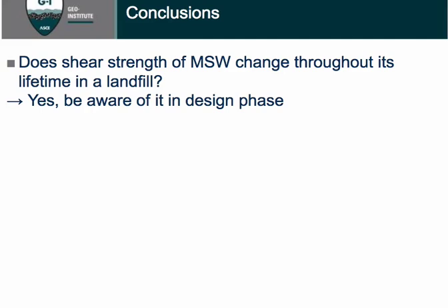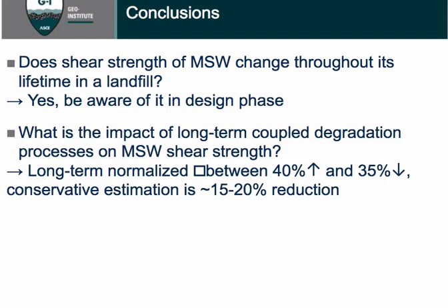So it's better to design the landfill, especially the landfill slope and containment system, in the beginning before the waste is actually in place, to make sure the slope will be stable and the interface shear strength will be stable, and so on. So we don't have any slope failures, which are really costly in many ways.